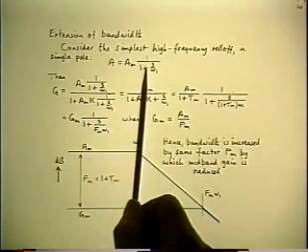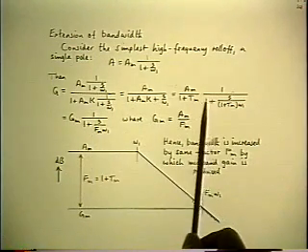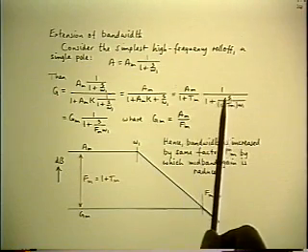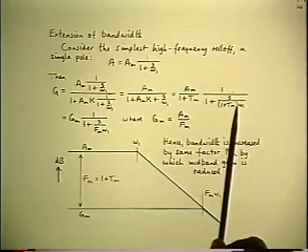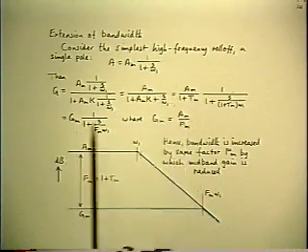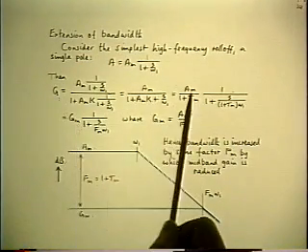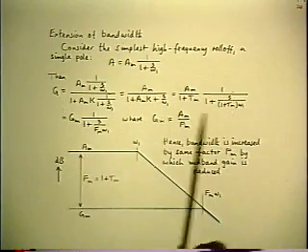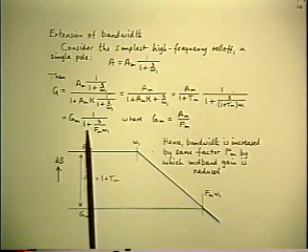So the direct substitution of the A into the formula and rearrangement into the factored pole-zero form gives you this result, namely a flat gain and a single pole. And you identify that flat gain, the coefficient in front, as the midband value of the closed loop gain, which is GM, and the pole is the pole in the closed loop gain, which is FM times the pole of the open loop gain.